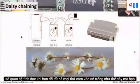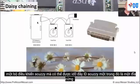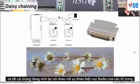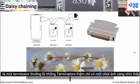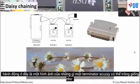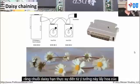Once you have everything plugged in, it looks a little like this, where you have a SCSI controller that might be ID 0. Here's SCSI ID 1, that's a hard disk. Here's another hard disk, and they're all chained together with different SCSI IDs, and at the end of the chain is a terminator. Usually these terminators even have a little light so you can see that they are active. Here's a picture of what a SCSI terminator might look like, so you can look at the back of your devices and see if you have one of those.